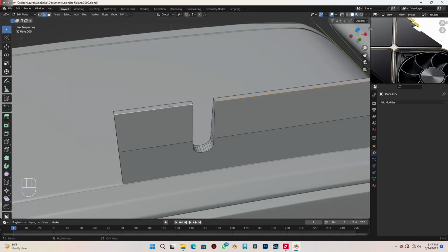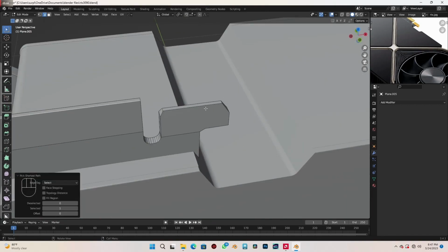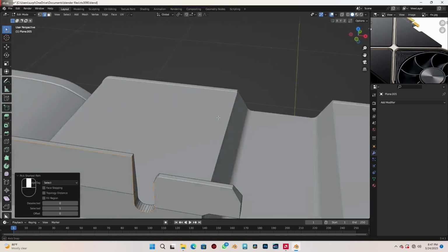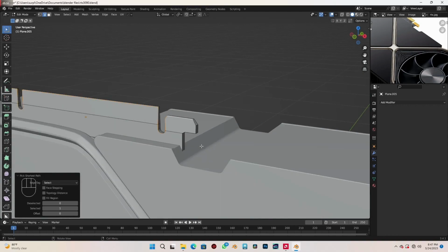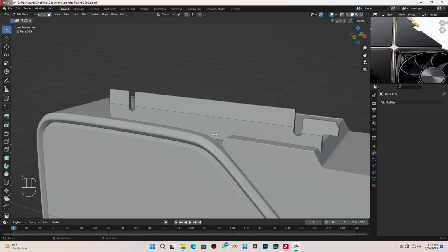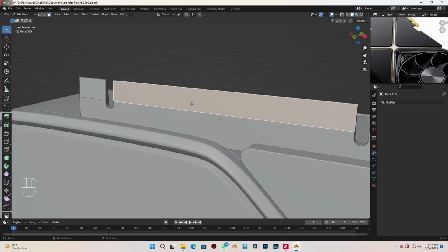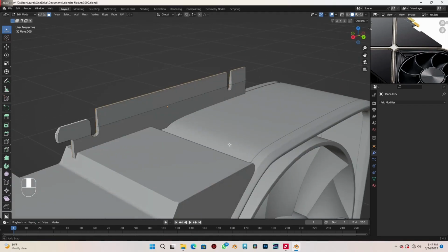Just select this edge and with Control, left click to select these, and Control, left click to select these. I think we can do this better with the first selection. So 3 to go to first selection, just select these and these, select this first, select this first too, and the same thing here, select these and these, select this first, and back to edge selection.